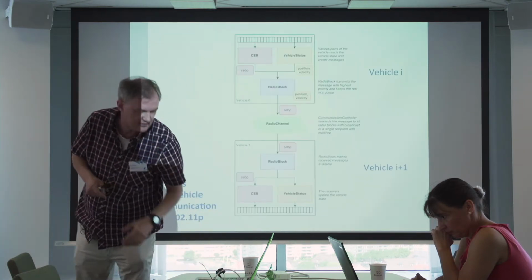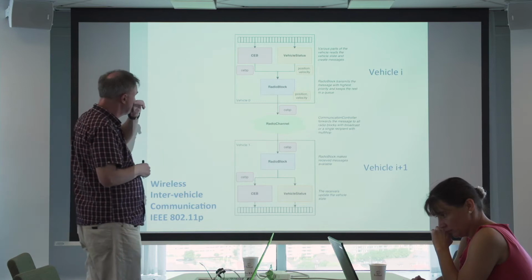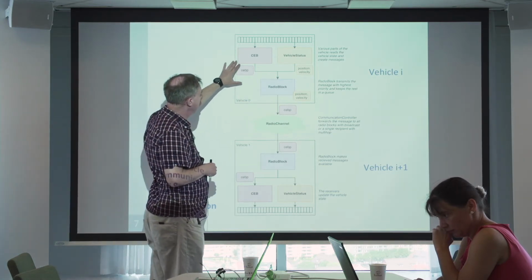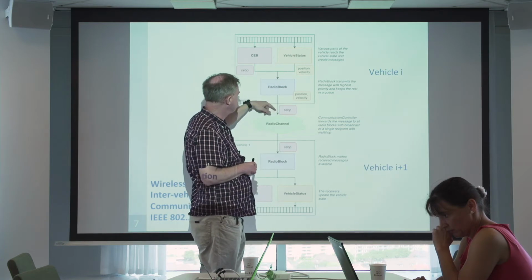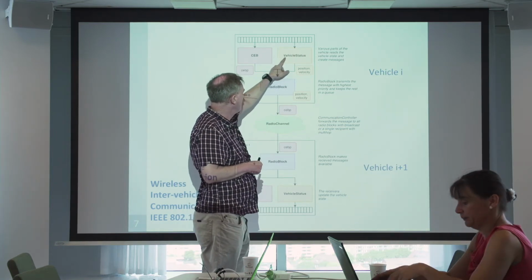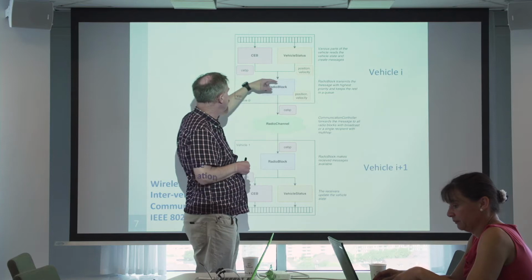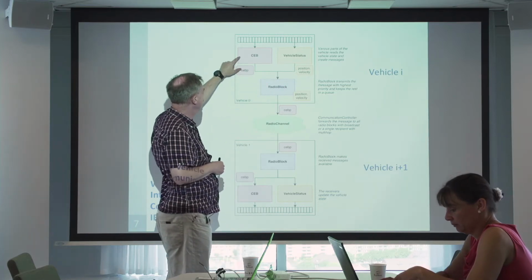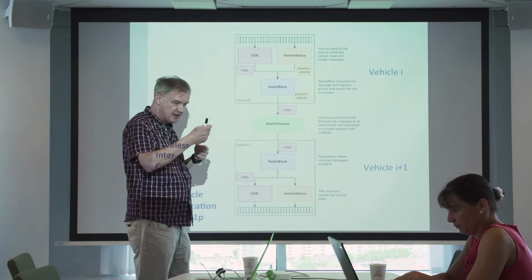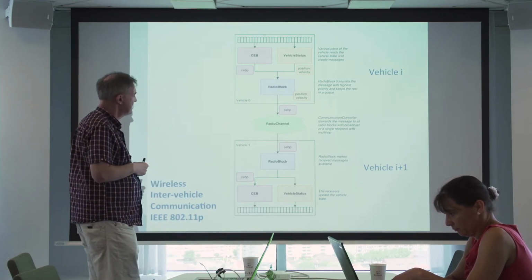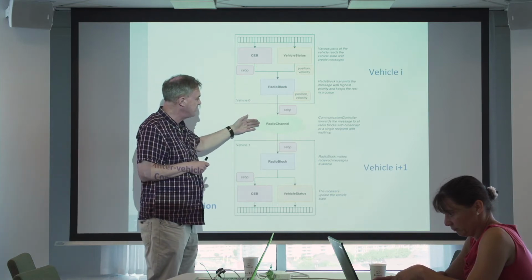And we also have, on top of the vehicle model, a comms model. So there's a block inside each vehicle that shares the bandwidth between, on the one hand, the GPS to relay the position and velocity, and on the other hand, the emergency brake protocol, which is also extended over time. And then that goes over a radio channel.